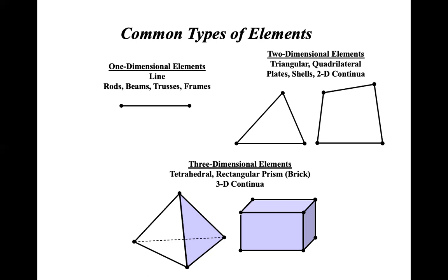But if you have, let us say, a plate or a cylinder subjected to internal pressure, or the plate is subjected to some uniformly varying load, in that case it is not one dimension. In the rod case we have length and area, so the lateral dimensions are not that much higher as compared to length, so we consider 1D elements. But in the case of plates, our width and length both are important. Thickness is not that important, so we consider it as 2D.